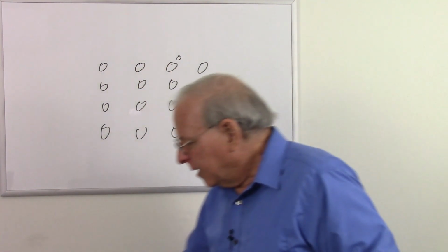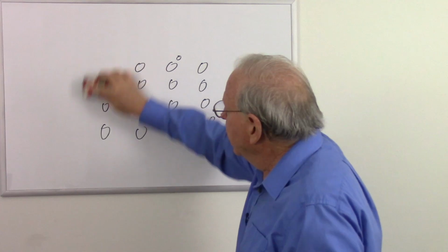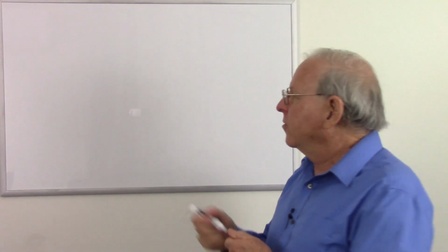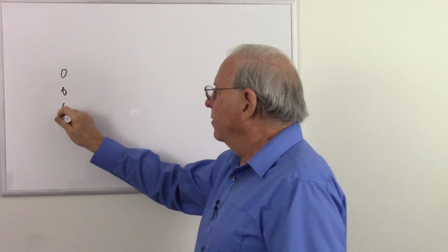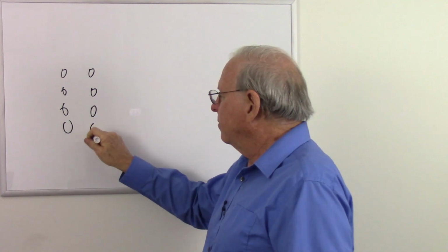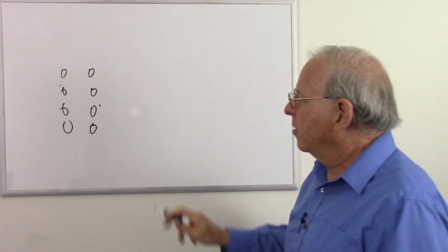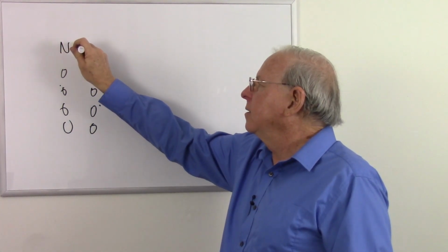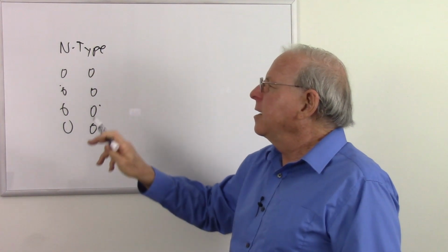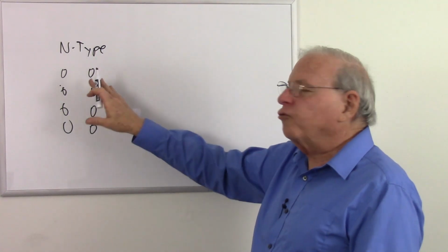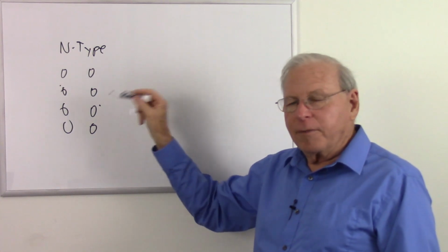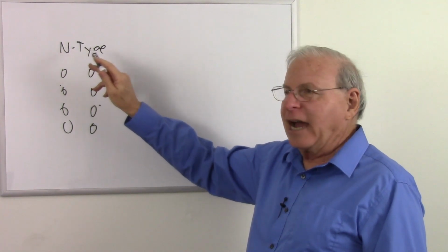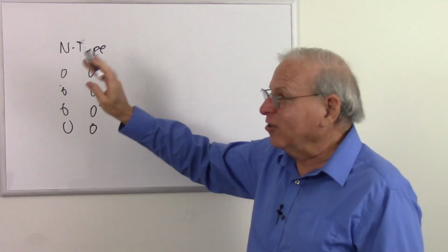We follow the holes. Now, there's a name for these types of materials. The material with the excess electrons is called N-type material. So, extra electrons. I'll keep this short. A couple of extra electrons, mostly silicon, a couple arsenics. We call that N-type material. Why? Because it's sort of negative, but it's not. It's neutral because for every electron, there is a proton, so it's neutral, but there's electrons floating around, so we call that N-type for sort of negative-ish, but it's not really negative.